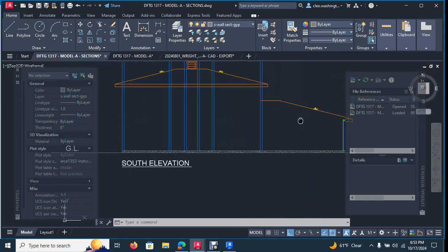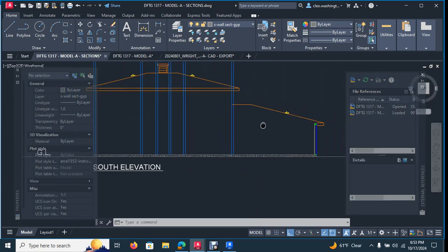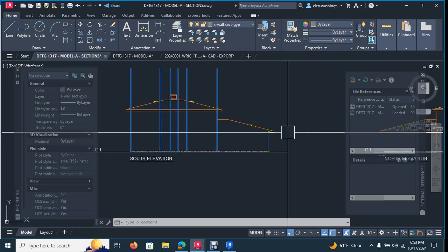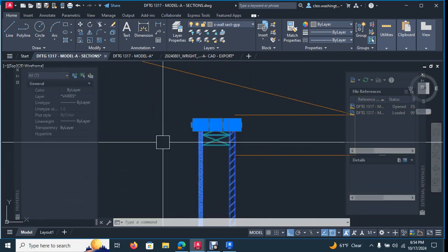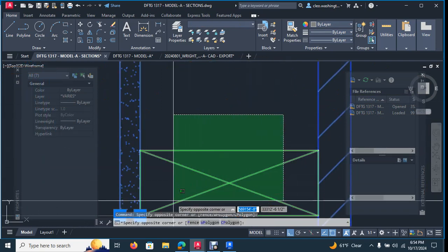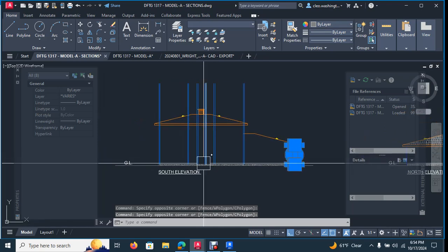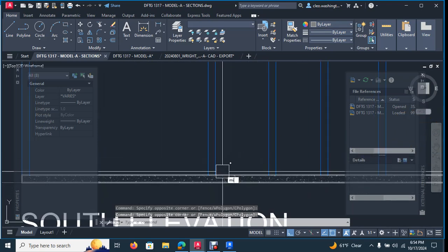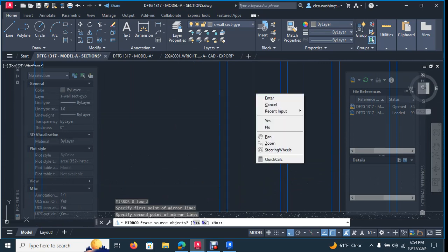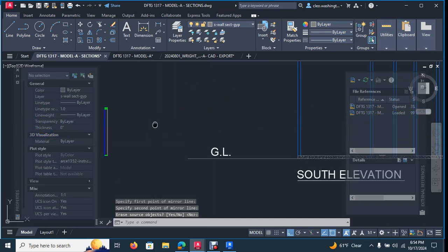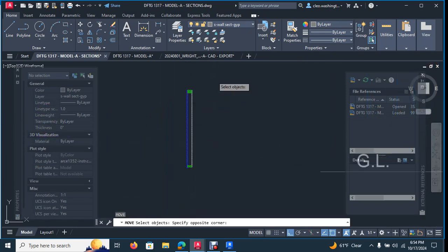We have our ceilings drawn in at 9 feet, all right? So what you'll do is, you'll take this one, okay? This entire wall setup, and you will mirror it. Let's just say MI, and just select here and drag up because you have the same exterior wall condition over here, except this one has a window in it, right?